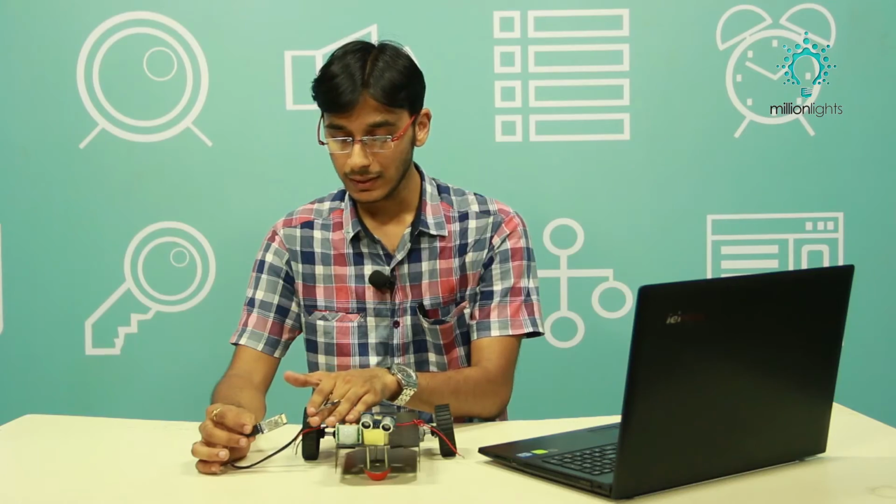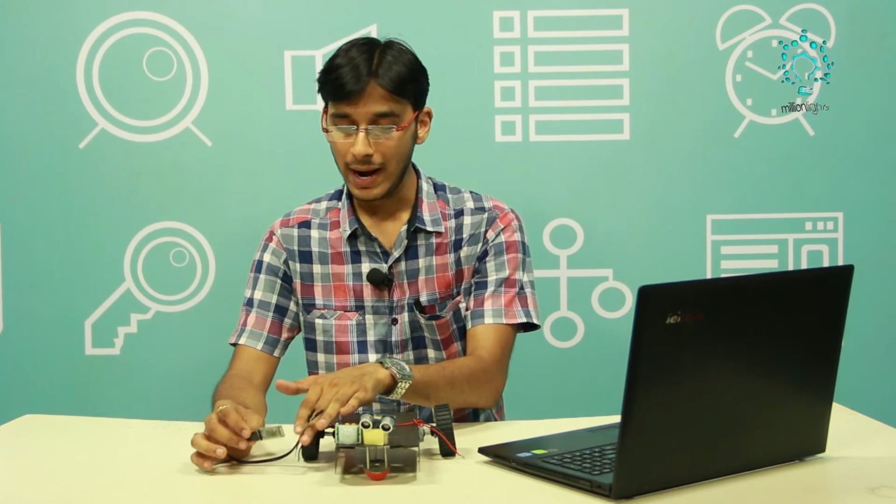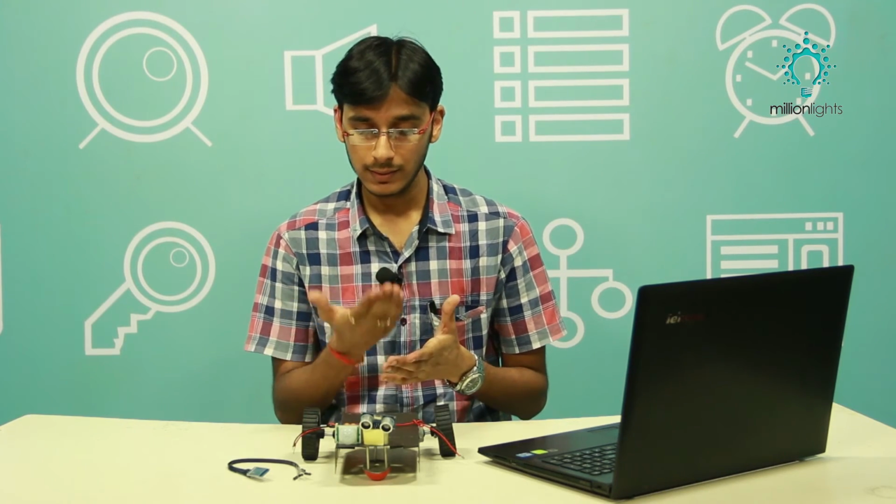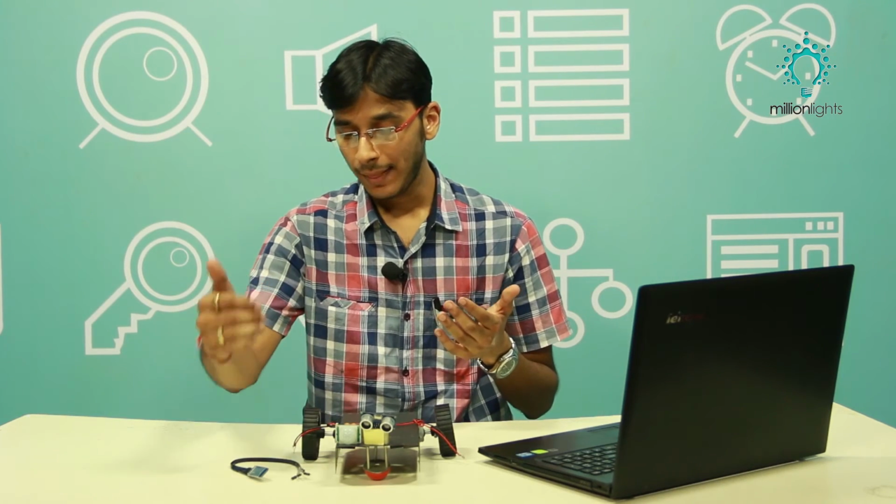We will just connect these 4 pins with Arduino, and after connecting it you can give instructions from your mobile. There is software, there is My Bluetooth Terminal, and a lot of various different software. You can use that, and as we transfer data between two phones, you can connect to this Bluetooth module and give instructions from your mobile app. Through Bluetooth it is transferred, those instructions are understood by this module and given to Arduino, and based on those values you can make this robot move.